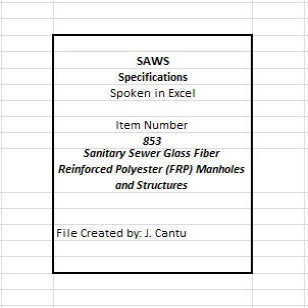service. 3. Excavation at manhole location should be at least wide enough to accommodate the slab specified and to provide working room around manhole. Ensure the depth of manhole is sufficient to allow between 2 and 4 throat rings for adjustment of ring and cover at top of final grade. Quarter marks have been provided on barrel to facilitate alignment. 4. Manhole base. Use initial backfill material to provide 4 to 6 inches of leveling base.